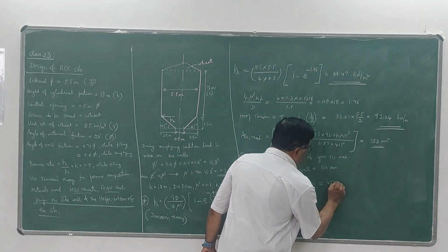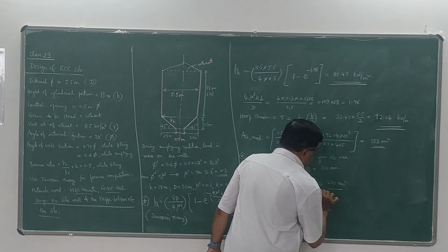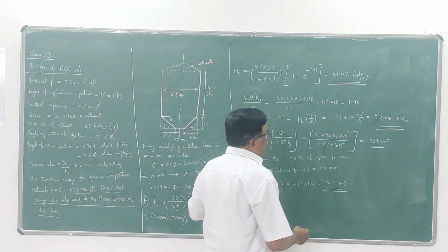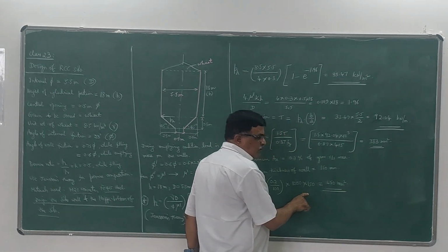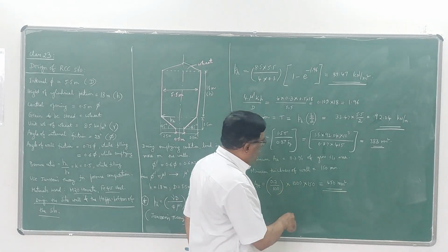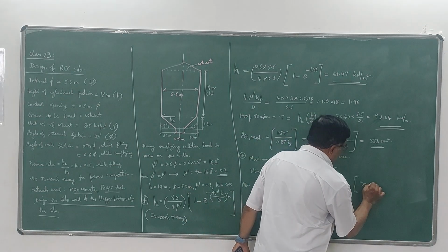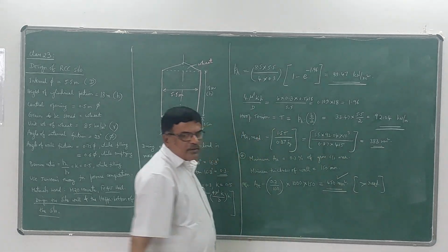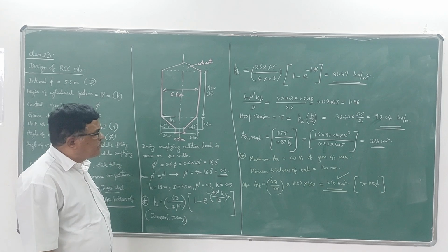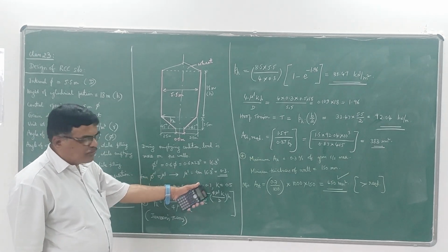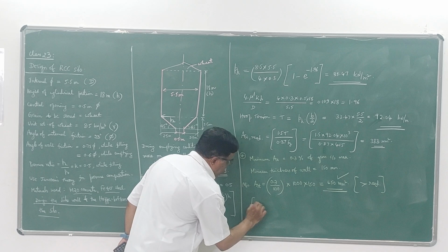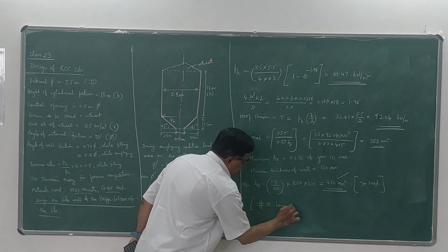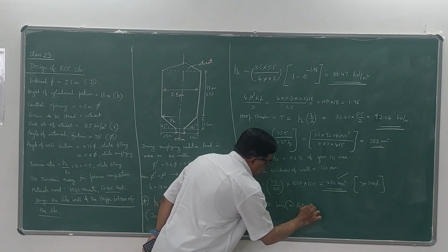millimeter square. So you have to compare this minimum reinforcement with the reinforcement required. Here the required reinforcement is less, but minimum reinforcement you have to provide, 450 mm square. So this is greater than required. Therefore we have to provide this much. So if you are providing 450 millimeter square as the reinforcement, you can provide Tor 10, that is 10 mm diameter bars at 140 mm center to center.